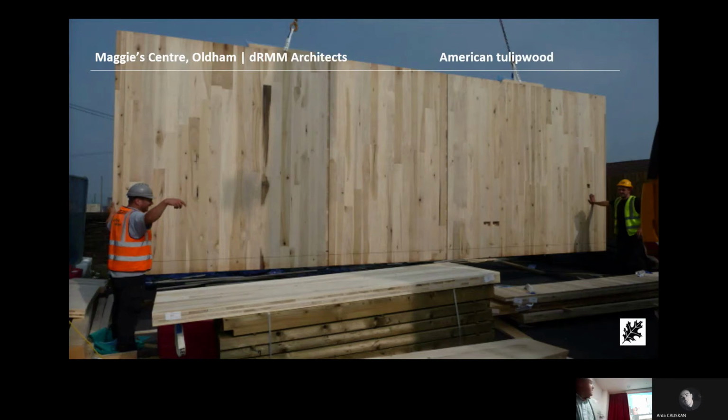Those are some of the panels. You notice that with the smile, the lamellas on the outside, they're always balanced. Either they're odd, like 3, 5, 7, 11. We're running horizontally because there was more layers because it needed to take more stress. Whereas these panels are just vertical panels taking a load. So they're 5 lamellas thick, 100 mil. So the outer layers 1, 3 and 5 can be vertical. There's not as much stress being placed on a panel as on the smile, if that makes sense.